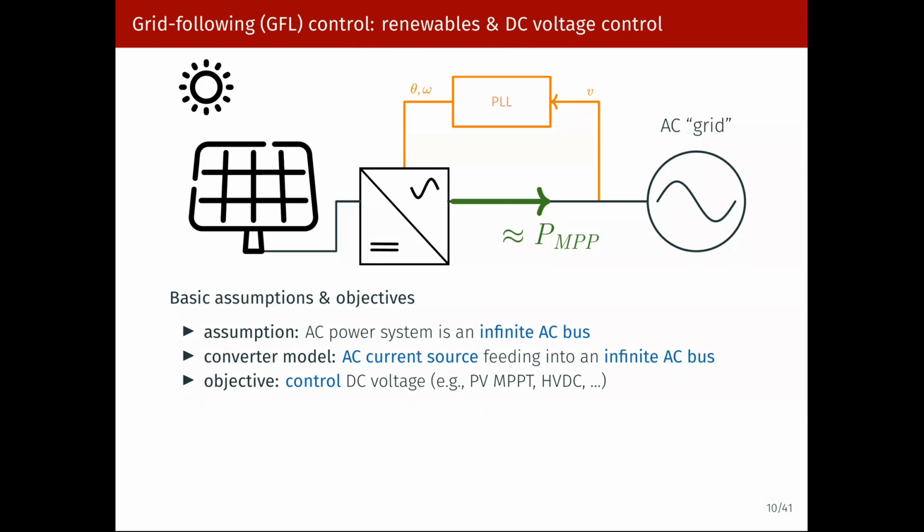And that would then decrease the rate of change of frequency, but it would not necessarily do a lot to the frequency nadir, depending on how the system is configured. Whereas the fast frequency response would basically be a primary frequency control response, so power injection proportional to frequency deviation, just doing that with a very small time constant versus the very long time constant of a steam turbine.